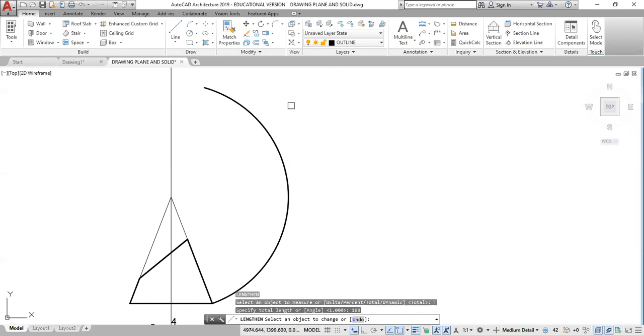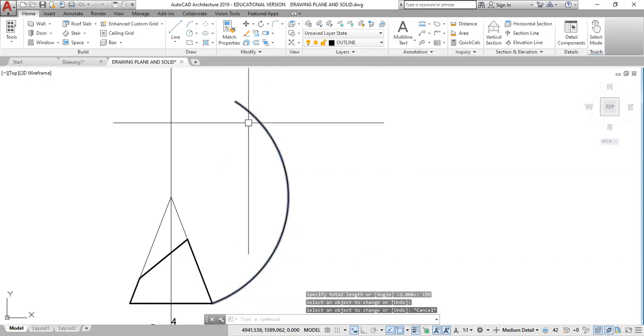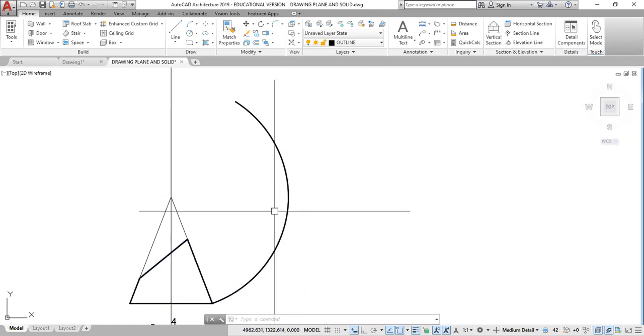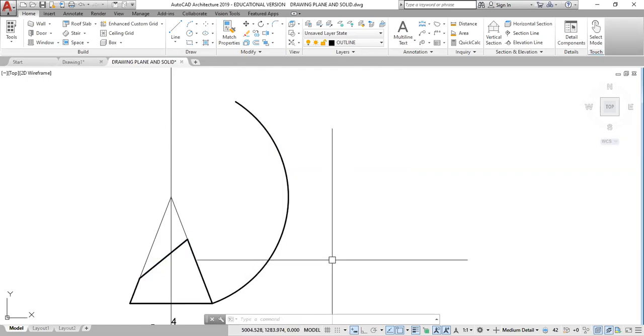It's important to note that the section that I select will determine where this will expand or reduce. If I touch down here, it will remove or add excess down here. If I touch on this side, it will add or reduce the excess up here. So I touch this side. Escape. So now this arc is a total length of 188.